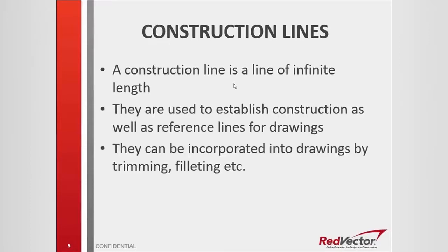Construction lines, once set up, can be incorporated into our drawing objects by using methods such as trimming, filleting, and so on. We commonly refer to construction lines as Xlines.